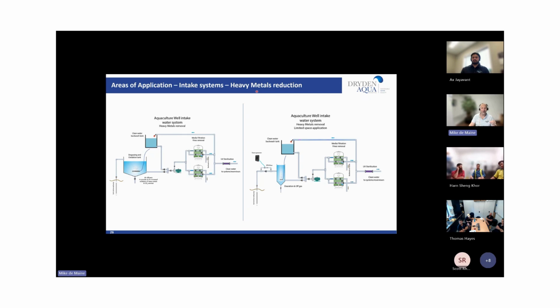That's a flocculation dose, which helps to flocculate particles. It also helps to increase the zeta potential of the water, in other words, changing the charge density on particles. Quite often, if your particles are fine, they're all very similarly charged, either very high negative charge or high positive charge, so they won't bind together. When we do an oxidation step with ozone, that helps to neutralize that charge and combine the particles together for better removal. In periods of algal events, that will also help to break down algal cells and then flocculate those cells.